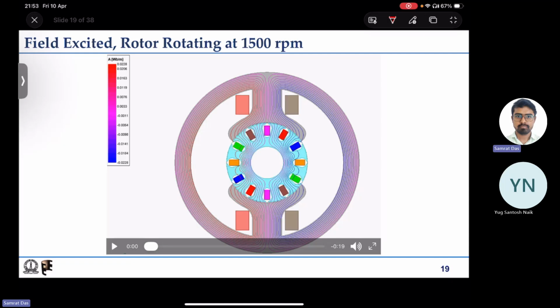The blue coil is also linked by almost all flux lines. For the red coil, some flux lines are certainly not linking it. If I indicate a flux line like this, it is surely not enclosing either of the red conductors, so the red conductor at that instant has less flux linkage than the orange and blue ones.